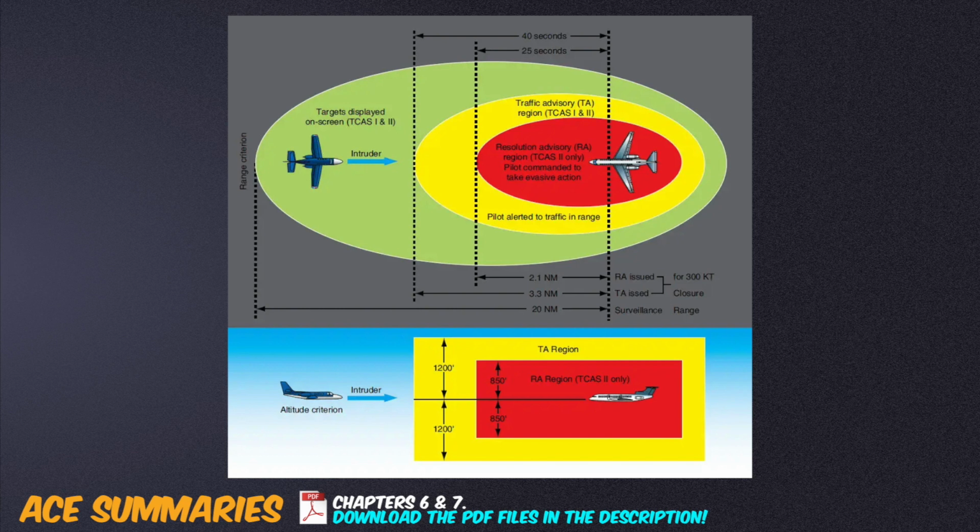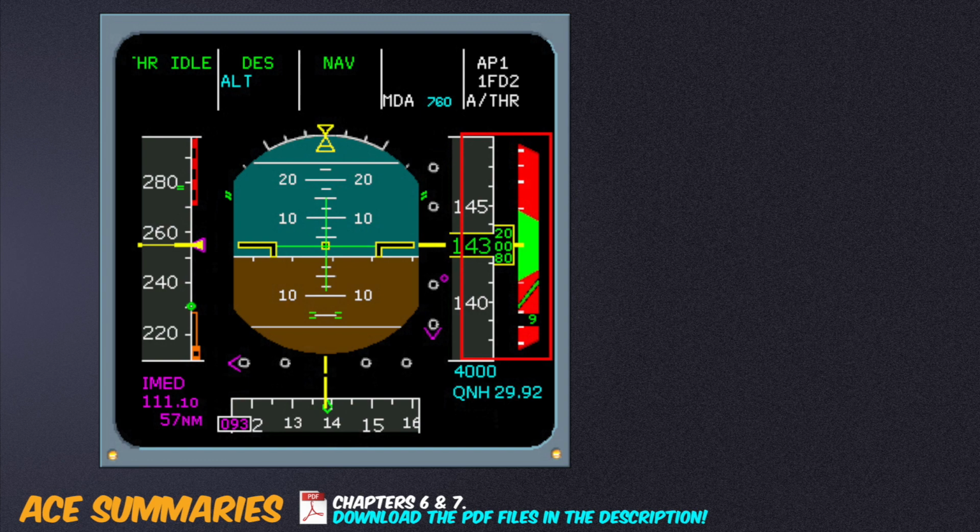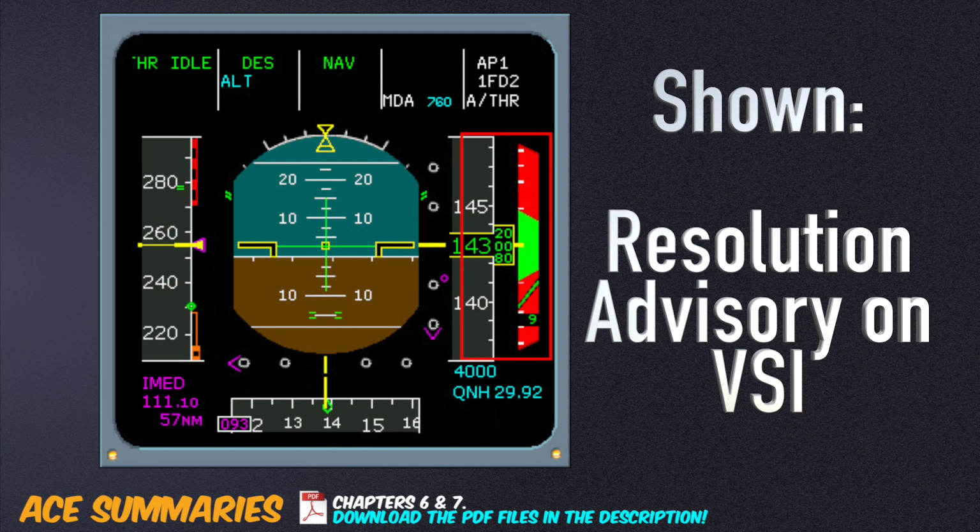In this case, a command, in the form of a vertical speed to be flown, is generated so that the pilot may follow this and avoid the collision. Resolution advisories are more important than ATC clearances, but TCAS use is limited to traffic advisories in dense traffic areas. Resolution advisory descent instructions are restricted below 1,000 feet, and all resolution advisories are inhibited below 500 feet. Traffic advisories are restricted below 400 feet.